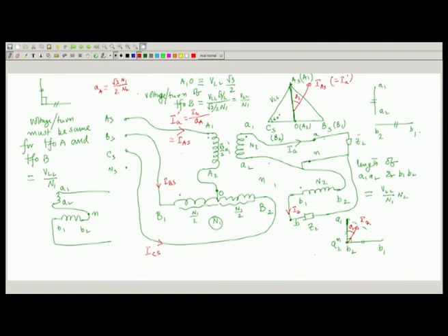Here also I could do like this. I A S will be such that, see this is what I have followed, but I could write it like this: the value of I A S I could calculate, the MMF produced by primary, root 3 by 2 into N 1, must be equal to I A into N 2.